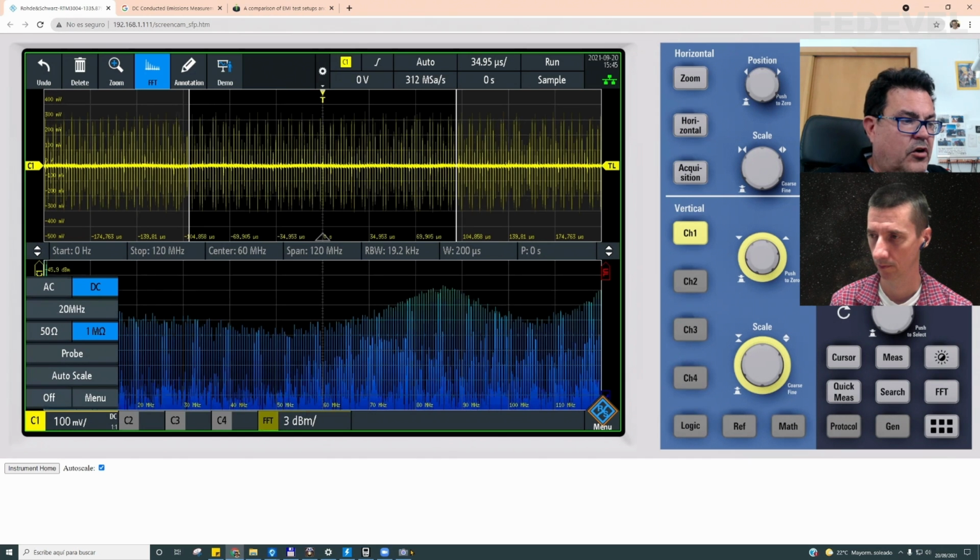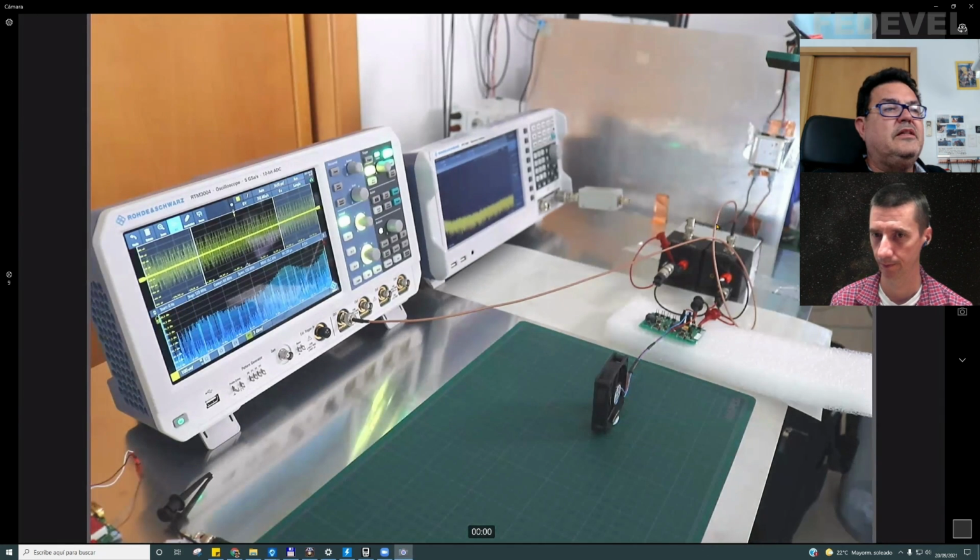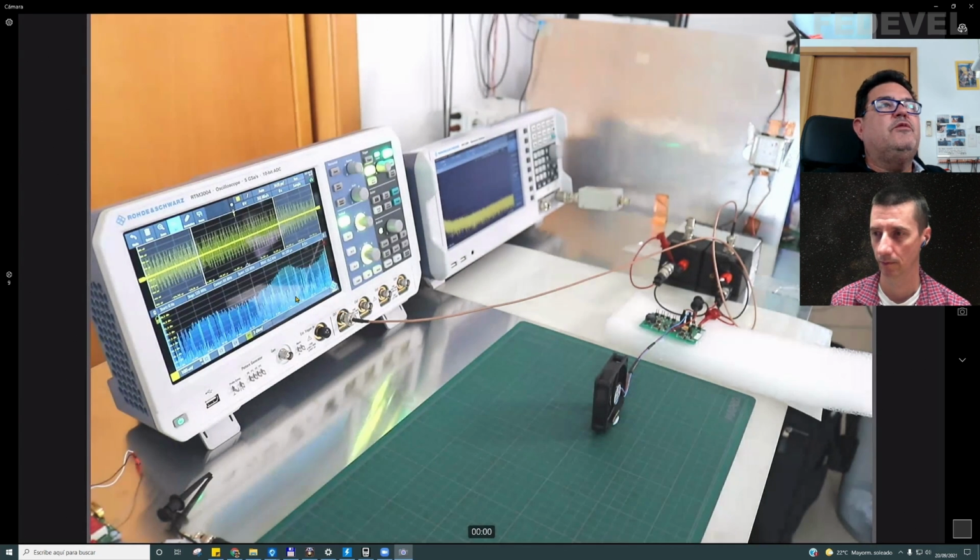If not, this is very important, because if you look at the screen, the signal is going in this direction through a transmission line that is 50 ohms in characteristic impedance. And at the input of the oscilloscope, typically you will have 1 megohm in parallel with 10 picofarads. This is a very high mismatching situation for this frequency range. So you will have a lot of reflection signal, and the signal on the screen is distorted. So to avoid this, we will put 50 ohms with the menu of the oscilloscope.